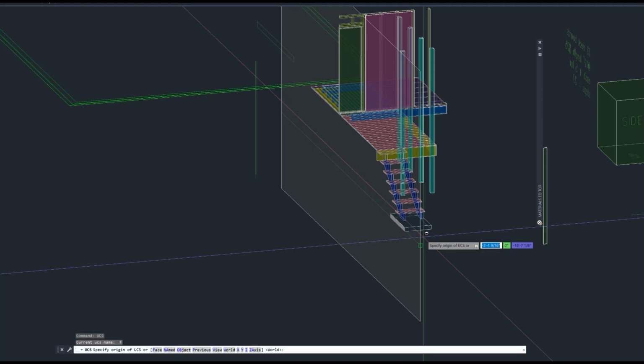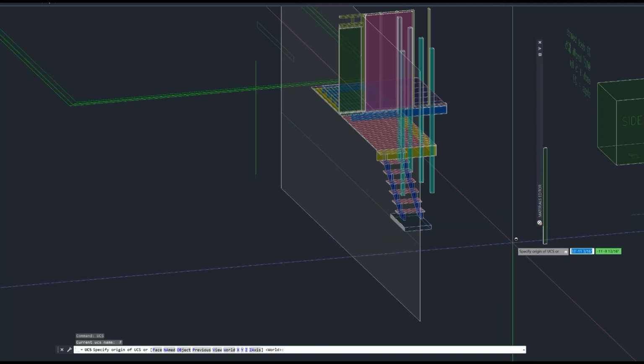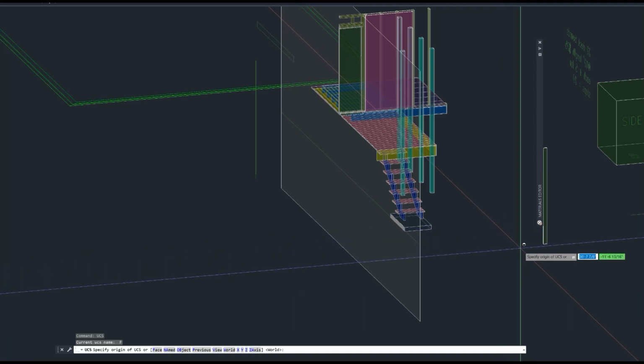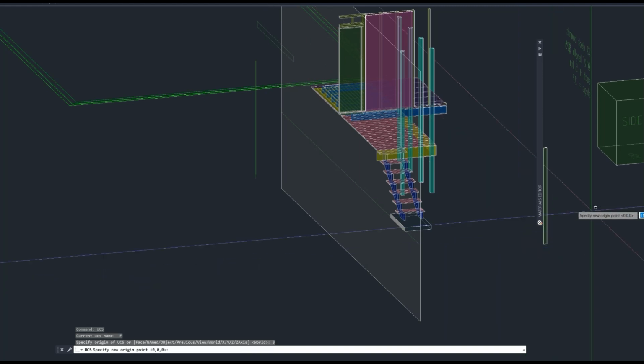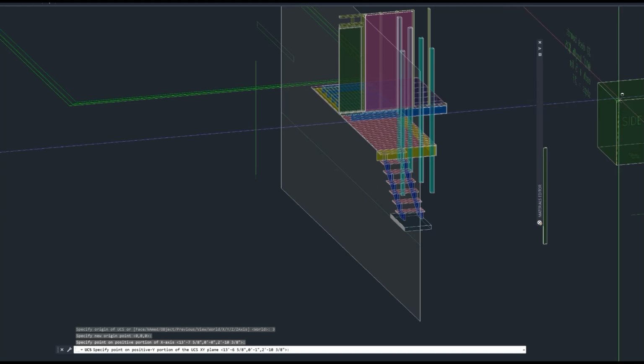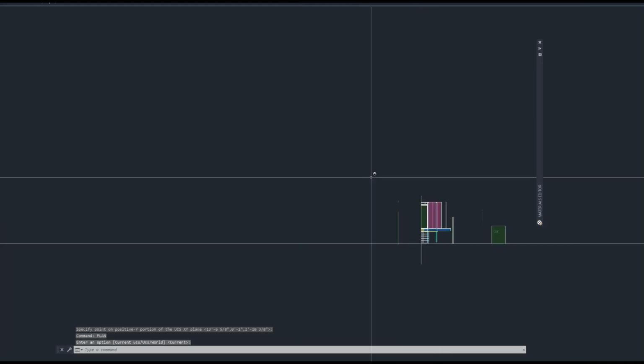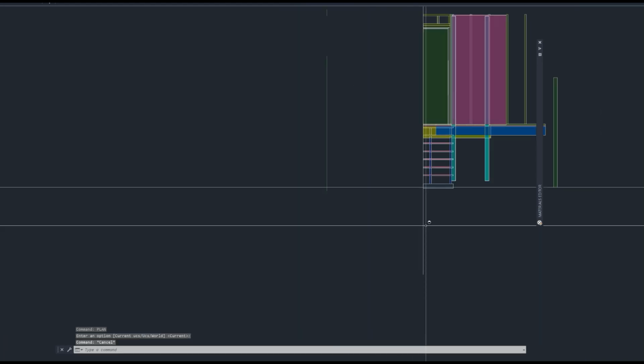Let's also look at one more component of the slicing tool, and that is rotation angles, if that will ever be required. My method is to first get to a 2D plan view and just rotate the plane into a random or precise angle. I use UCS, then a command called plan to switch the view. Rotation angles can then be more specific.